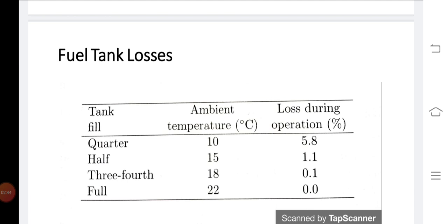When a partially filled fuel tank is open to the atmosphere, the partial pressure of the vapor phase hydrocarbon and the vapor pressure of the liquid are equal, and they are in equilibrium. If the temperature of the liquid is increased, say by engine operation, the vapor pressure of the liquid will increase, and it will vaporize in an attempt to restore equilibrium.